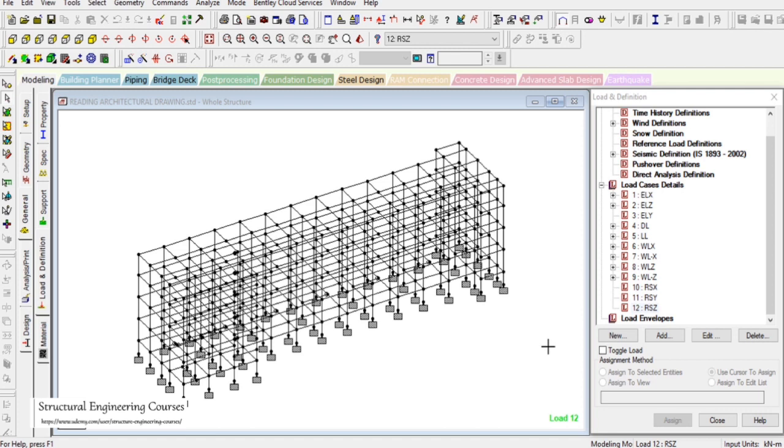And the problem with the dynamic earthquake method is that we do need to scale the forces that are coming from the dynamic to the static. So we cannot just define the response vector cases as 1, 2 and 3 and just design the structure. As per all the country design standards, for American, we do need to match up to 85%, and for India, we do need to match up to the 100% of whatever results we are getting here.